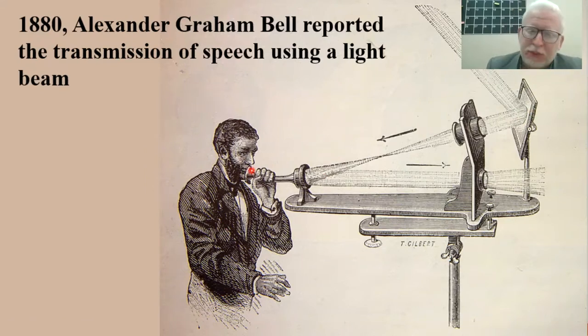So typically now, Alexander Graham Bell's voice is the message. The light emitted from the candle is a carrier signal. This is an optical carrier signal from the transmitter to the receiver. And this is what we can frankly say is an optical amplitude modulation, where the amplitude of the optical signal is varying while Graham Bell is talking. And then this is a detector, and here is the receiver. This is the primitive, the first initial optical system across the world.